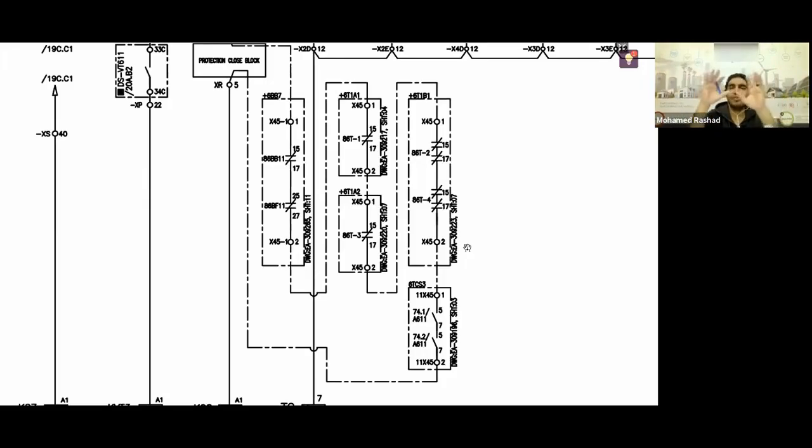I'm speaking to you generally. I'm not focusing on protection. The people who attended with us are the transformer protection and line protection. I spoke about that in detail. But here I'm talking to you about why the transformer has main protection 1 and why it has main protection 2. There's also bus bar protection, and you have breaker failure protection. These are the 4 things that can trip your feeder or your breaker. Either main protection 1 is activated, or main protection 2, or you have a breaker failure on the bus bar, which trips your breaker, or the bus bar itself has an issue, which trips your breaker.